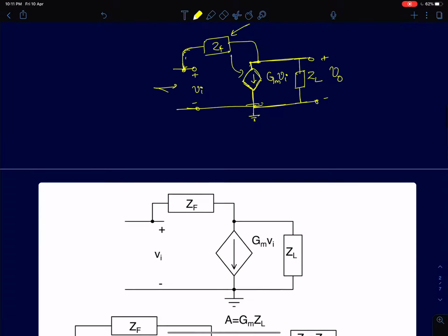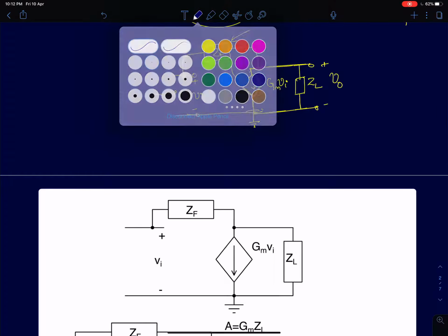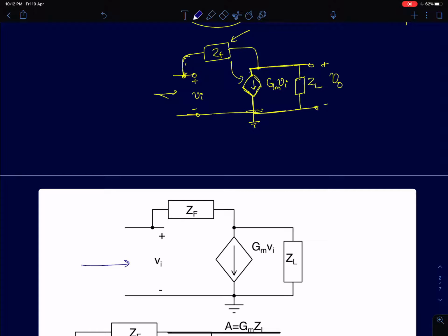To see that, I have shown here the equivalent circuit, which better approximates a MOSFET. Now we are interested in MOS based circuits, and in finding the input impedance. So we'll apply the standard trick. This is a Norton equivalent, a current source and resistance in parallel. We'll just model this as a voltage source and resistor in series.